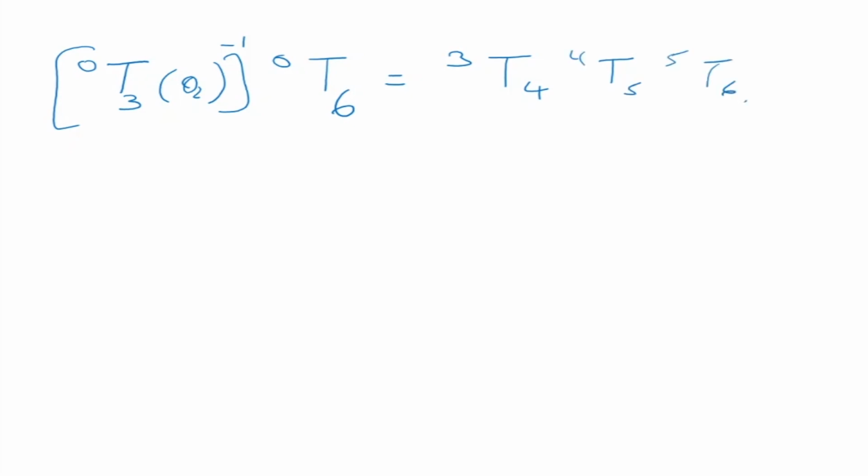Okay, we said that we are multiplying in a particular sequence. First we did, if you remember, 0 to 3, and then we did 4 to 6, and then we removed theta 1. So now in this matrix, theta 1 and theta 3 are known. So what is not known is theta 2. So theta 2 is unknown now. So on the left hand side you have one unknown. On the right hand side you have theta 4, theta 5, theta 6. Okay. So now what we do on this, let's call this equation number 4.